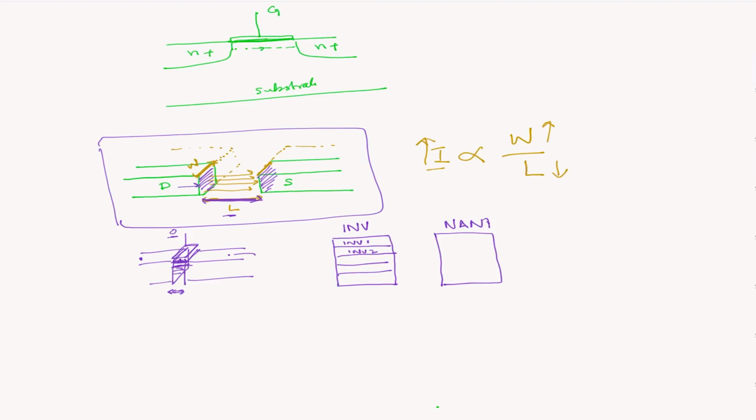So what we did, I think at 14 nanometer or 22 nanometer, I'm forgetting right now where the actual transition happened, since it was hard to control it through these two, and you wanted to get more control of this channel, where the current is flowing, we turned the gate into a slightly different structure. We said, okay, from the top we are controlling here. We want to control from this side and the back side as well. So let's try it again.